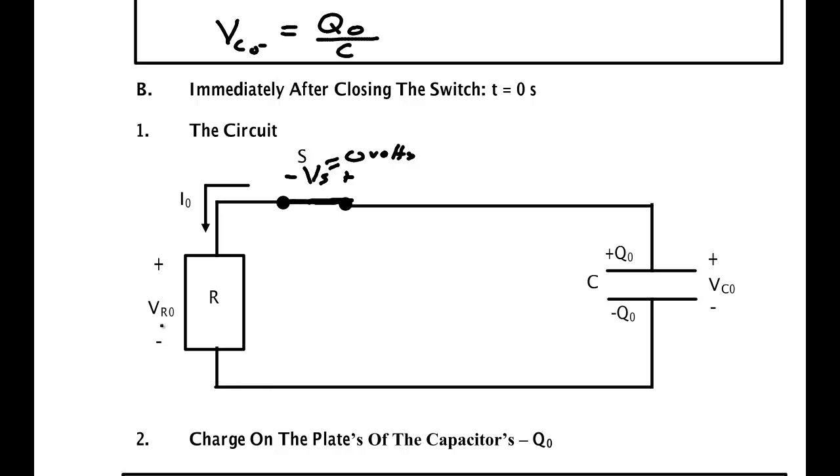But if that circuit gets broke, and if you've unplugged the television set, it doesn't matter. If this circuit is broke, this charge and this voltage stays on this capacitor with its energy. And I said that energy is enough to vaporize a screwdriver. Even with the TV unplugged, if you touch one of these capacitors and you don't know what you're doing, you potentially could kill yourself.